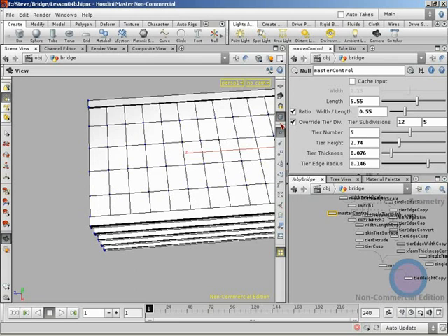So the way I'm going to do this, the way that Peter did this, was to basically create a new line node, and set the translate Z positions of the 2 points on that line to the translate Z positions of the first and second point, so point 0 and point 1 of this curve we've just resampled.